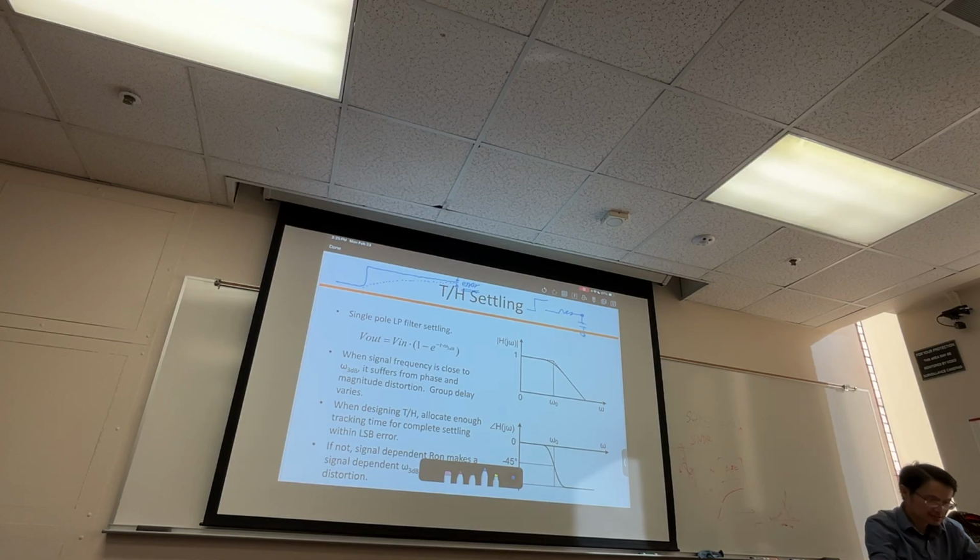Below your delta. The error is below LSB. 1 delta or 1 LSB. Very good. In fact, throughout the semester, whenever I ask you this kind of question, you answer, yeah, less than 1 LSB. 99% you're right. Okay. Why is that? You say that less than 1 delta you don't care? Because you won't quantize it to a different one.